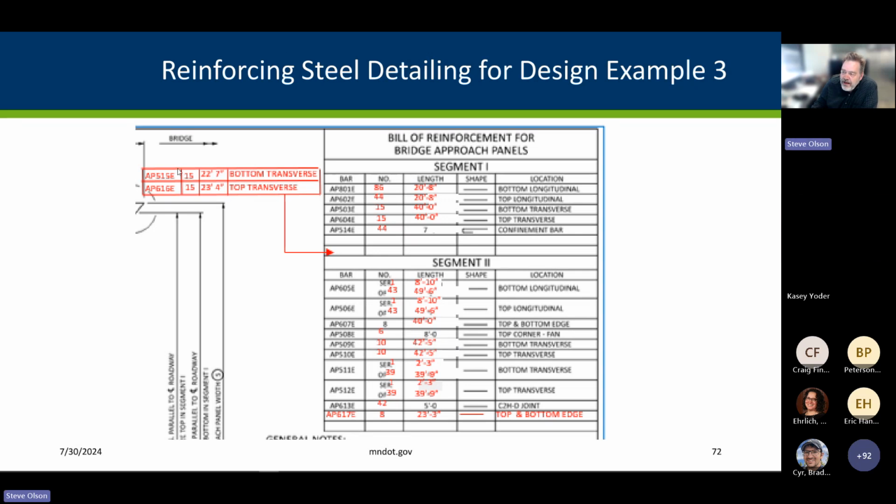We do need to add the extra bar marks, and there are choices to be made when you provide reinforcing bars that are in the cross section. We theoretically could provide a single bar in the 503 or the 604 bars and just have all the splices at the same location.